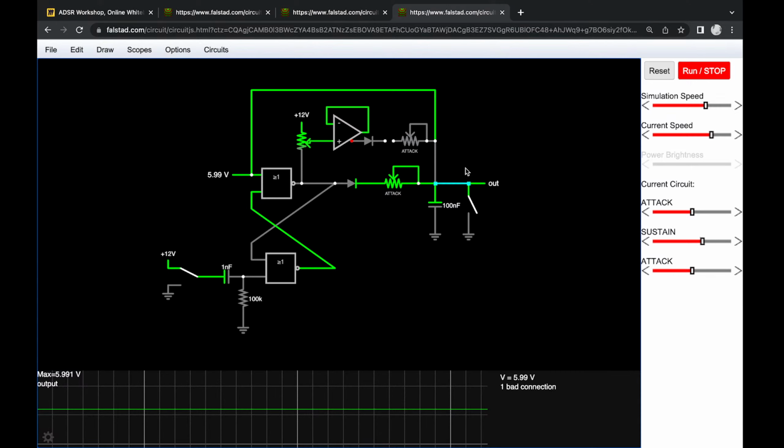Oh, I've put it too far down. That's unfortunate. So it needs to go one up, and then this needs to go up two. Boom. And then the diode, like I said, so this is the wrong direction, right? If we want to discharge into the op amp, if I put it here, the problem is we couldn't discharge because the diode would be blocking it, right? Because diodes are one-way streets for currents.